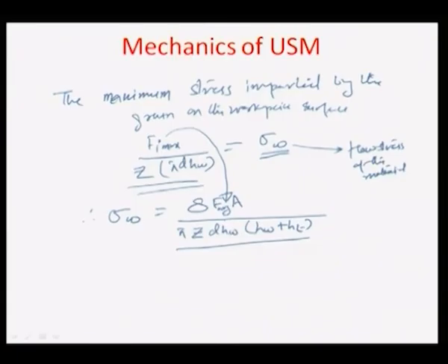So, it is quite reasonable to assume that the depth of penetration is inversely proportional to the flow stress of the material, as long as the load and the indenting sphere's diameter remain the same.